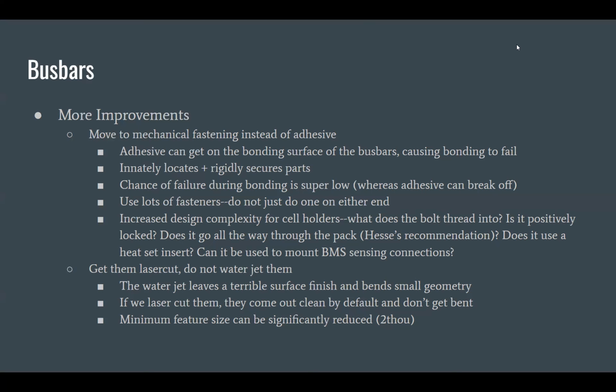And then, yeah, obviously this comes with the other additional problems, like I already mentioned, of complexity. Now you need to figure out, okay, cool, can you do a heat set insert? Do you need to bolt all the way through the pack? How does that work? How do you positively lock it?